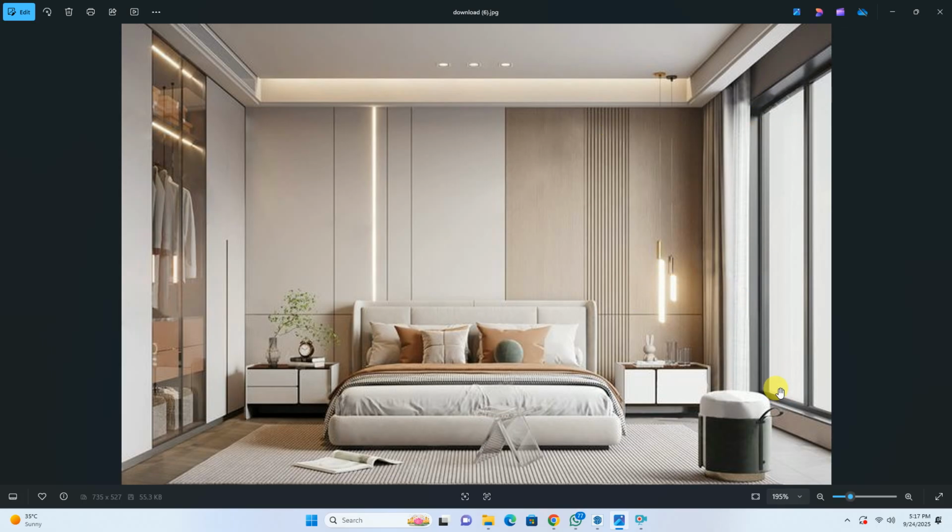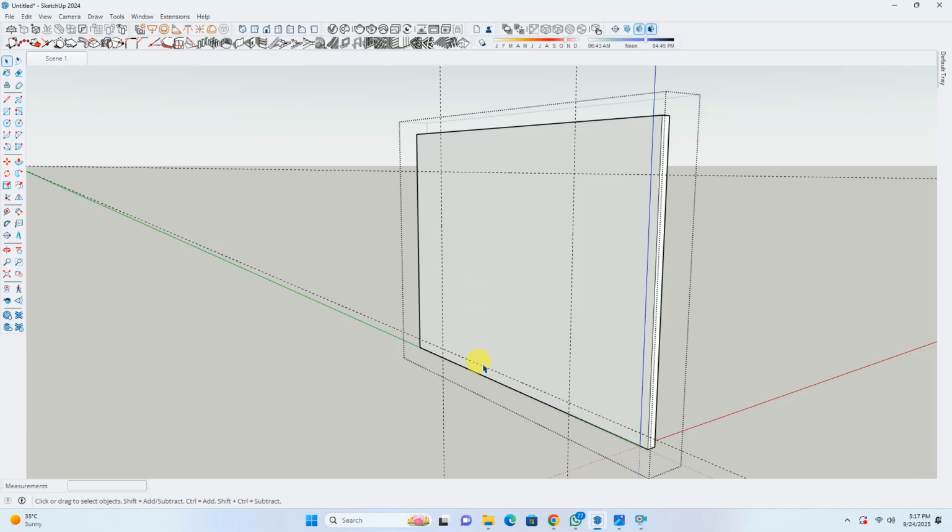We won't use wooden profile for this section because this is the exposed part and it would be in contact with water also. So that's why in balcony side we generally use either UPVC or aluminum. Okay, so we can see that this height is about 9.5 feet. Presently, for this design we'll be using aluminum, and if we want to convert it into UPVC, we'll reduce it to a height of 9 feet only.